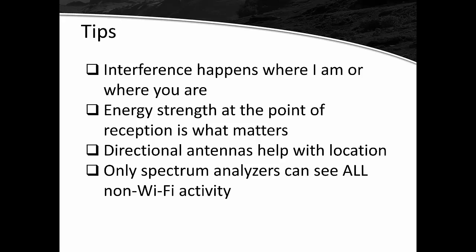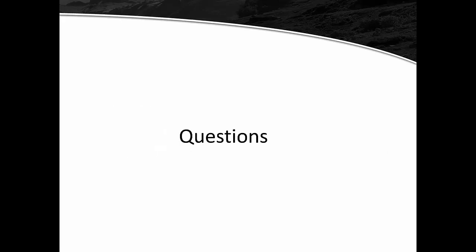So if you want to be able to see the non-Wi-Fi activity, you're going to need that spectrum analyzer. Now you might run into a specialty adapter somewhere that says you can do Wi-Fi and Bluetooth all in the chipset and things like that. But the reality is, if you want to see non-Wi-Fi, you need a spectrum analyzer because it looks strictly at the RF energy.